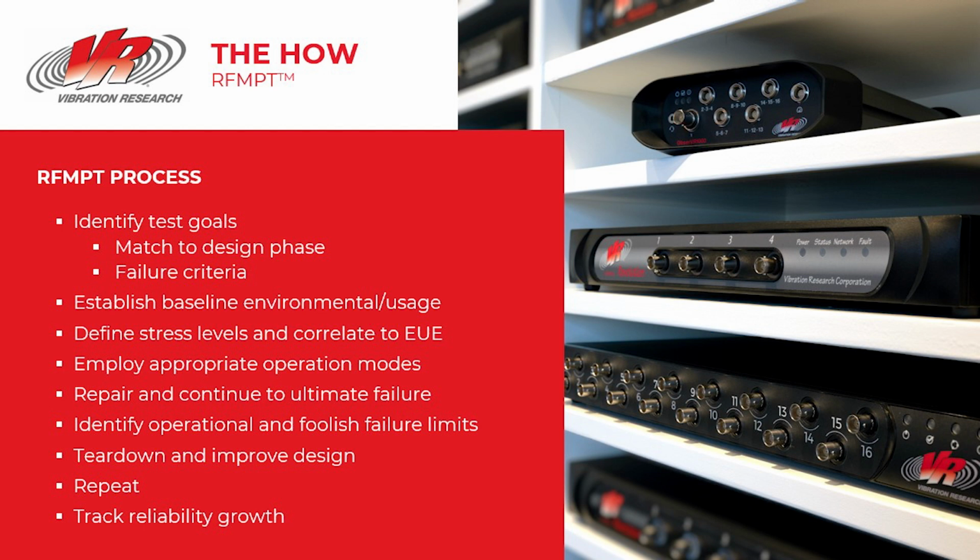The operational parameters related to any mechanical or electrical cycling should, where possible, be included in the test setup. These characteristics should be well articulated in a comprehensive DFMEA with clear expectations for what inputs are critical and at what levels and cycle counts are needed to replicate a full life cycle of the product. In addition, which failure mechanisms drive which failure modes, how they are represented in the test setup, and finally, what performance criteria is used to establish a bona fide failure are critical to running a successful test.